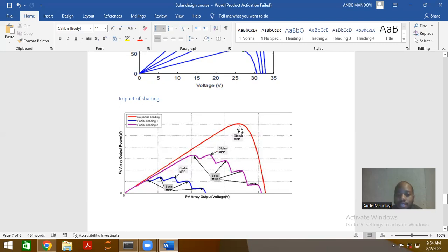But yeah, these are things that you need to consider. You want to avoid shading at all costs, because you will not be getting as much money. You won't be getting bang for your buck if your panels are shaded. This is more than a 50% decrease in your power output. And over here, it's almost more than a 75% decrease in your expected power output, all because of shading. And that obviously is affected by the degree of shading and all of that, and how you've done your system. You're going to use microinverters and whatnot. But typically you want to avoid shading as much as possible.